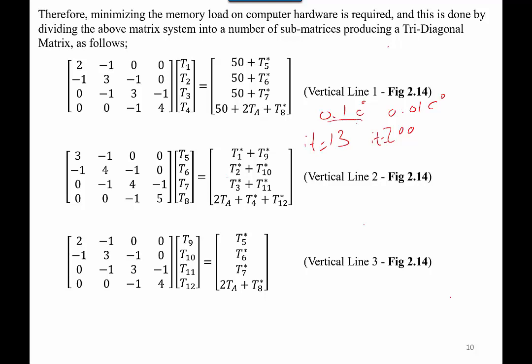When this number goes smaller, the iteration number will go bigger, and this will cost you more time. And if you are studying another field like chemical concentration or something else, if you take 0.1, it will be bigger for this field of study. Maybe you take 1E minus 6. It depends on the nature of your problem.